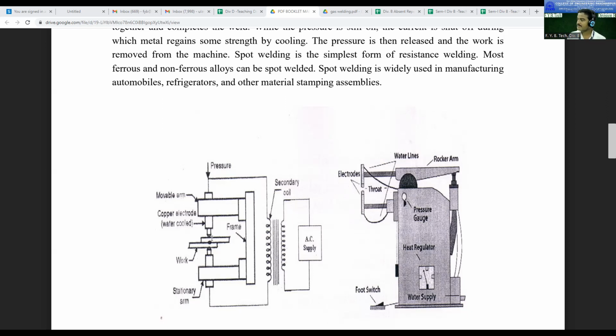If you follow arc welding, the plate will get burned immediately. म्हणजे काय होतं की ही जी प्रोसेस आपण फॉलो करायची कधी जर थिकनेस आपली जी प्लेट आहे ते कमी आहे एकदम आणि तुम्हाला दोन पार्ट जॉईन करायचे आहेत तर मी प्रेफर स्पॉट वेल्डिंग. पण जर तुम्ही या ठिकाणी आर्क वेल्डिंग वापरलं तर कमी थिकनेस असल्यामुळे लवकर बर्न होत असते. So to avoid this problem we prefer the resistance welding.